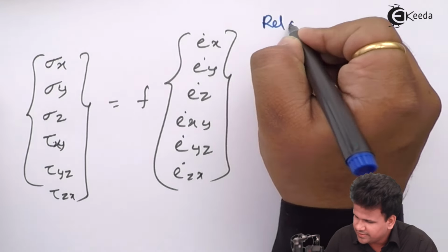Along with this, we'll neglect this term for the time being, and then we'll substitute this term. So this is ∂/∂y of τ_yx. So this is μ into (∂u/∂y + ∂v/∂x). So these terms will have, and lastly ∂/∂z of τ_zx. So that is equals to μ into (∂w/∂x + ∂u/∂z), which is equals to the right hand side of the equation.